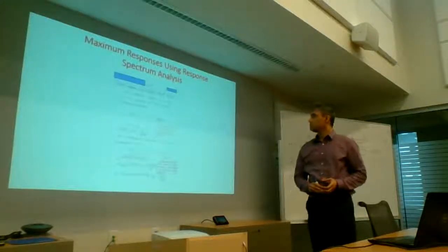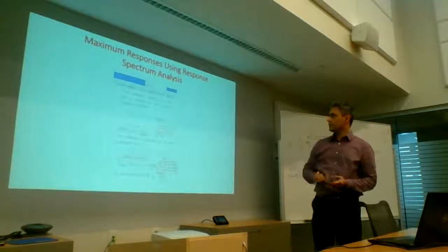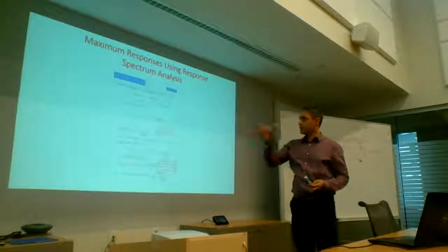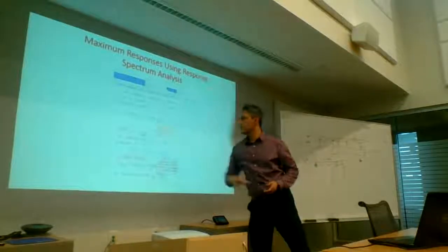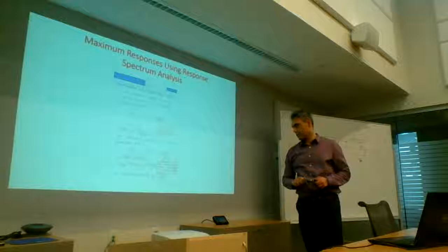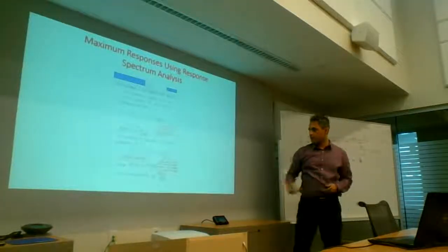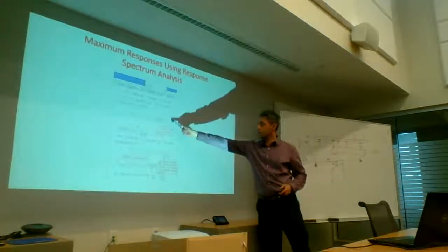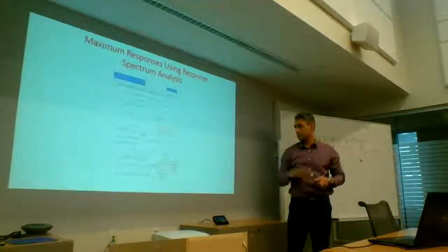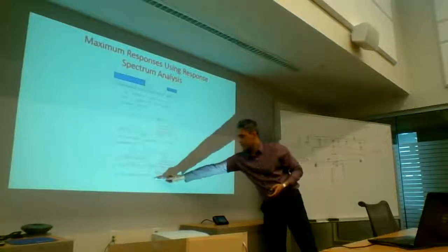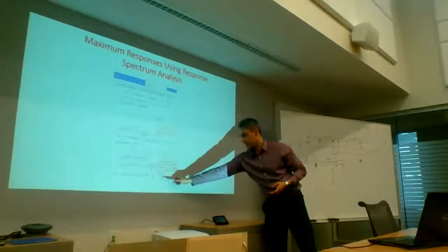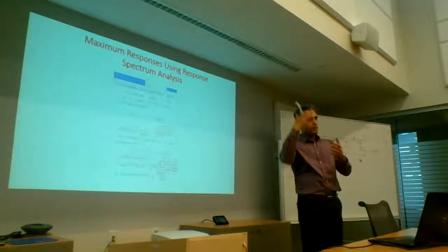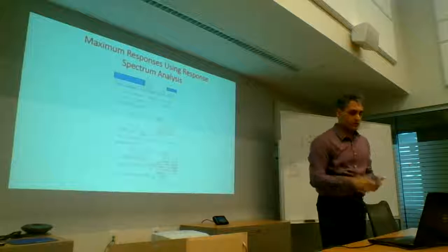Okay, so when we do the earthquake response, we bring in a vector of unit values in there, because then that works. It's just this L is equal to 1. You can look at Chopra if you want to see a bit more detail of it. So this is the case where you don't have a P, you've got ground acceleration. The only difference now for the participation factor is not phi and Tm. There is a 1 there, because these are matrices, so to multiply them to get a number, you need to have a vector of 1s. That's all it's there for.